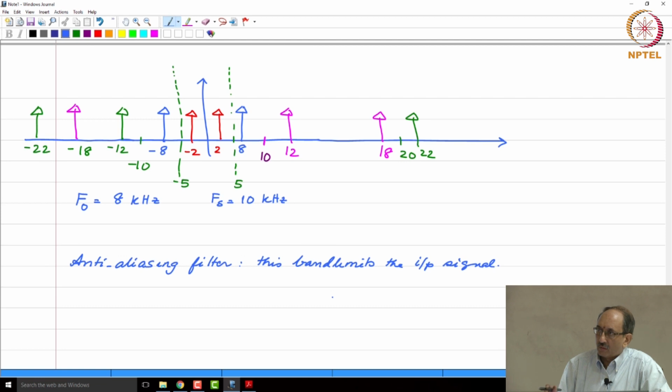So, this is on one side. Now, you have to compare this with a signal. If you do not do this band limiting filter, if you do not introduce this and band limit the signal, if you sample, you are going to cause aliasing, because the signal is band unlimited to begin with. So, no matter what you do, you are going to distort the given signal. The question is, which is better? And the answer to this is this anti-aliasing filter at the front end is better,